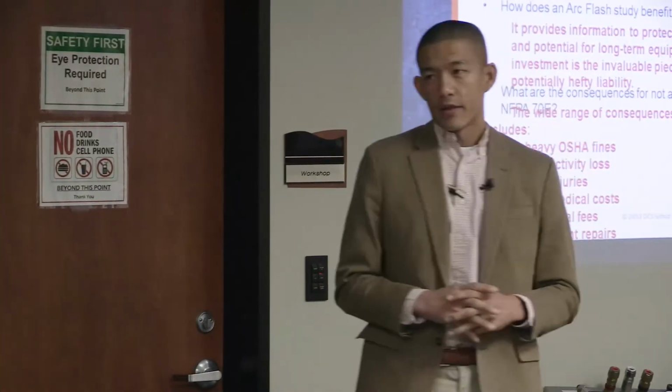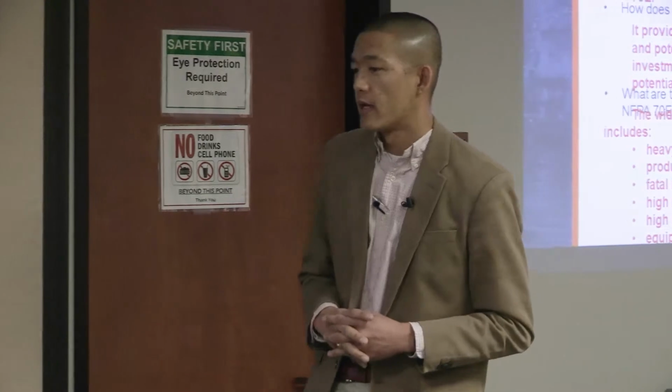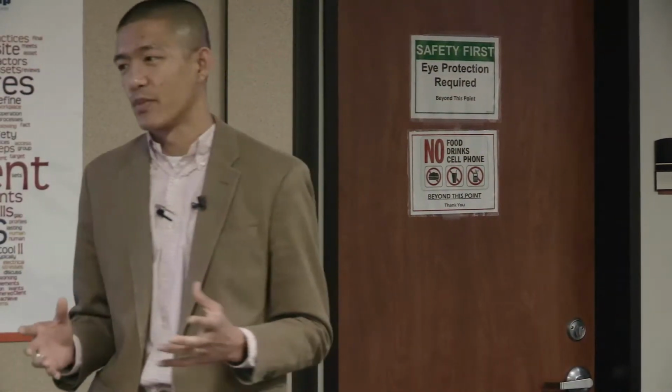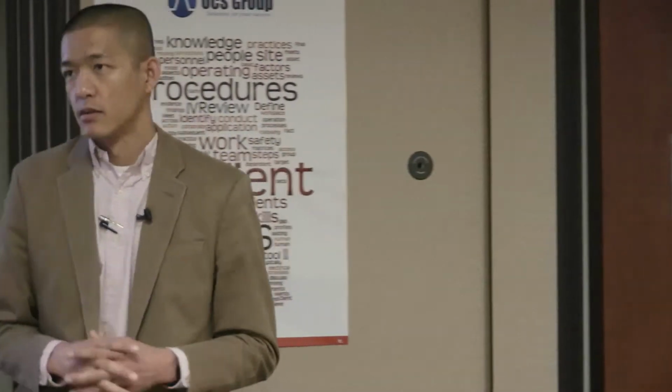different. Another thing that has been changed is more of a transition to a risk assessment. Actually, I shouldn't say more of a risk assessment, but they're focusing a lot more on the risk assessment rather than actually pushing people to do more of a calculated study. It is my personal and conservative belief that using the risk assessment method and tables that are listed there in the 70E can actually be quite confusing to the people that are actually working on the equipment.